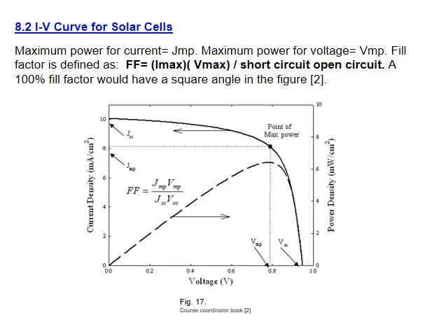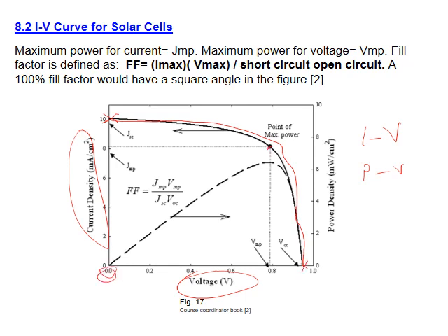Now, the IV characteristic, and there is also the PV characteristic, by the way. In the IV characteristic, current is here, voltage on the x-axis, and the curve is this curve. This represents the characteristics of the cell. It means high current here with zero voltage, or high voltage here with zero current, and the maximum power is approached in the middle here. Definitely it's supposed to be rectangular, but this part is lost because of many effects, resistances inside the cell, as I will explain later.